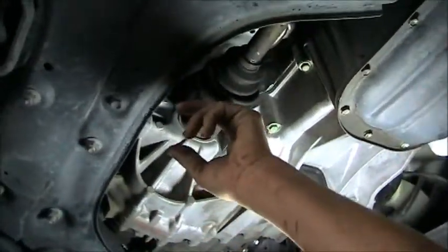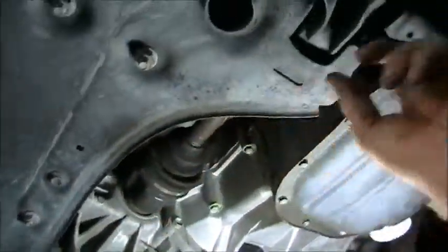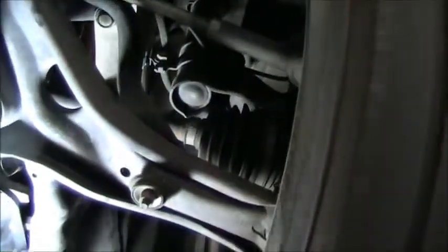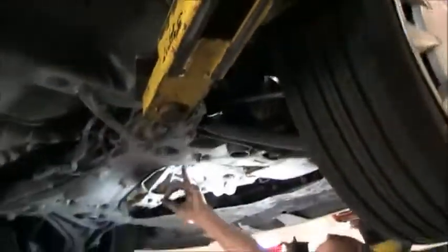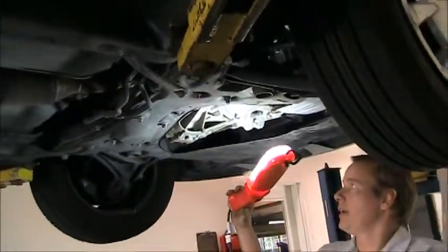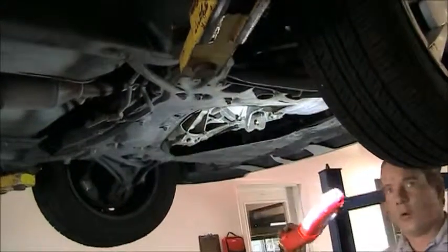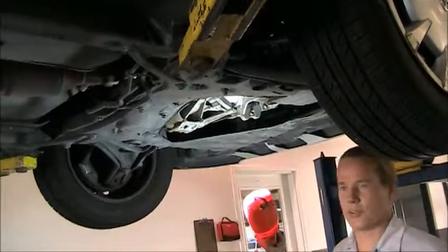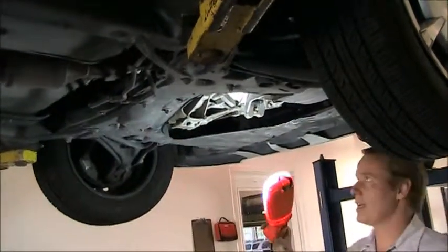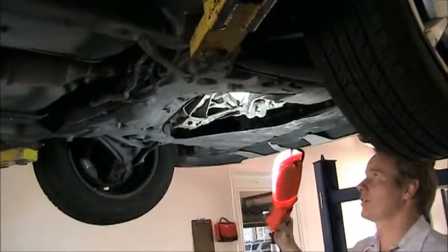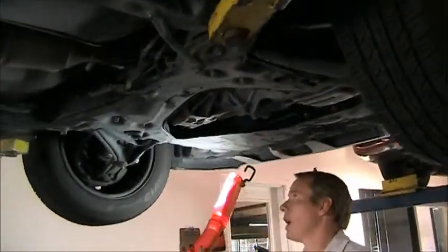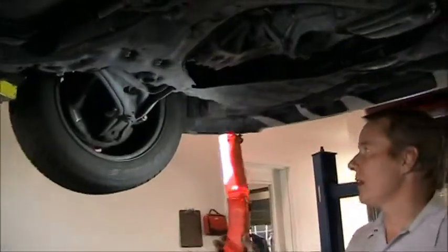Now we have an axle on this side, which is right here. It connects out to the wheel over here. You can see as I turn this, the wheel is turning and the axle is turning it into the transaxle. If you notice, one wheel is going one direction, the other is going opposite. That's because we have the differential. The vehicle's in gear, which means the crankshaft can't turn and the wheels will go the opposite direction. That's really all I can show you on the front wheel drive.